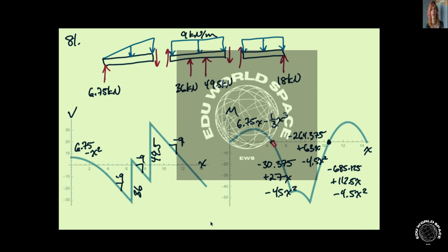In this region, we can again get our moments. We start at 0, and our function is given by this quadratic expression, which would be the integral of this function defining this curve. We have minus 4.5 in front of our x squared term instead of 9.